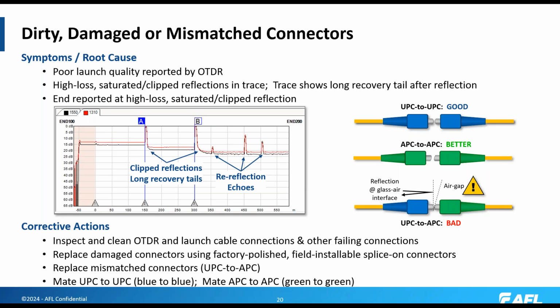If cleaning doesn't remove the contamination, it's likely that your end face is pitted from mating one or two dirty connectors, and cleaning isn't going to fix that problem. So now you need to replace those connectors with field installable fusion splice or mechanically spliced on connectors.